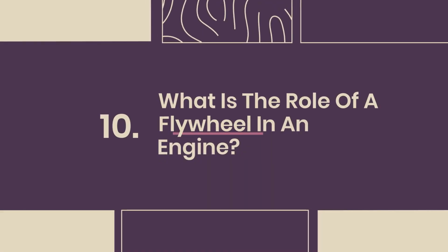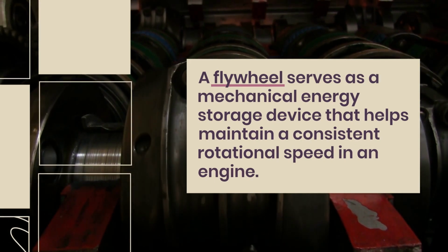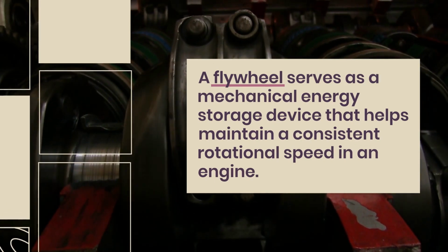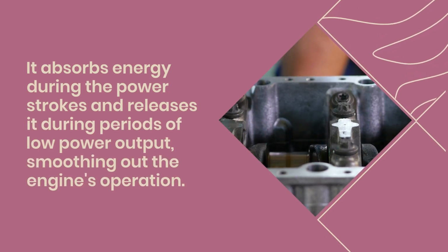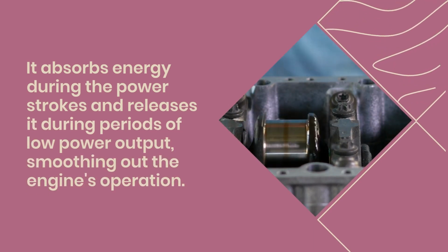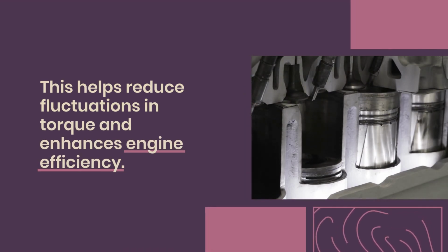10. What is the role of a flywheel in an engine? A flywheel serves as a mechanical energy storage device that helps maintain a consistent rotational speed in an engine. It absorbs energy during the power strokes and releases it during periods of low power output, smoothing out the engine's operation. This helps reduce fluctuations in torque and enhances engine efficiency.